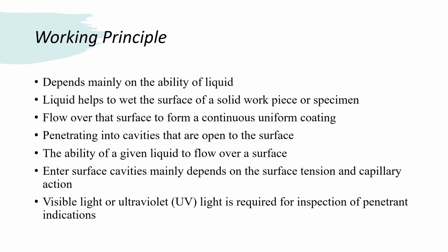Fluorescence describes the release of light energy by some substances when they are excited by external radiation such as ultraviolet light. In penetrant inspection, when the particles in the fluid are struck by the incident ultraviolet light, they are excited to a higher energy level.